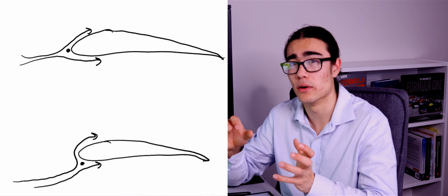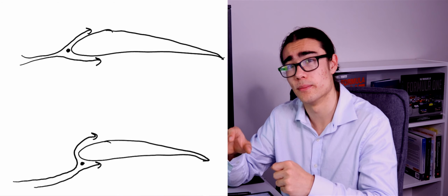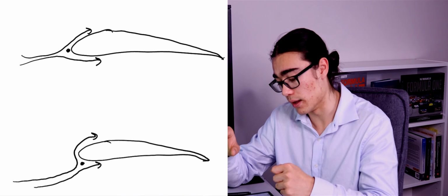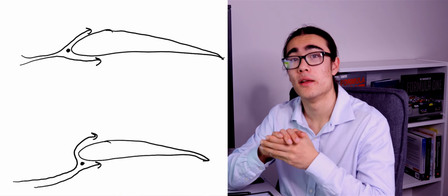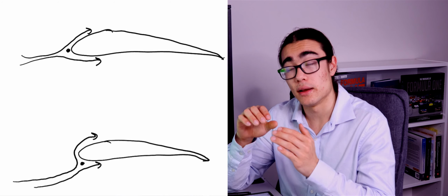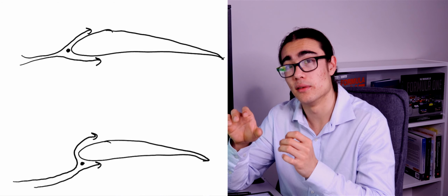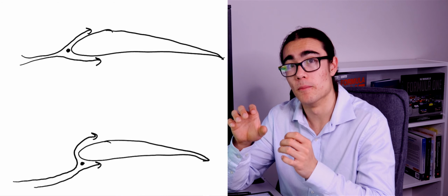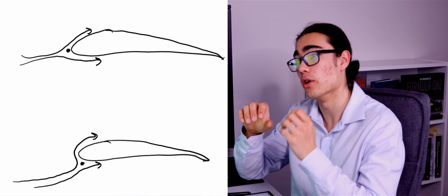In this case, it's very, very minor, but I think that's why we're seeing that slight increase in coefficient of pressure on the underside of the airfoil. The other thing to note is on the upper side. When we've decreased our stagnation point height, and especially in this case because we've got the cylinder, we're actually extracting a little bit more curvature out of the flow earlier on.